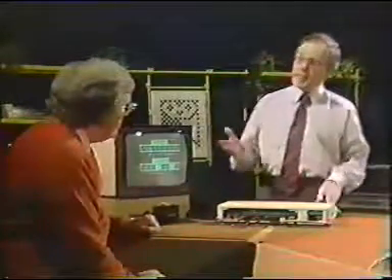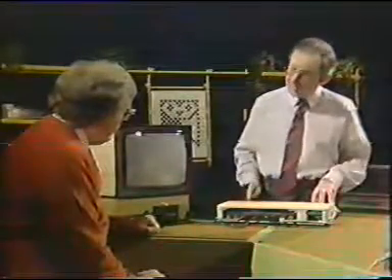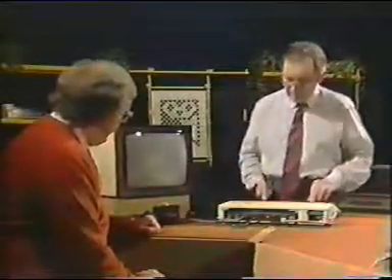Now, we're actually running a program at the moment, but I could stop the program and talk directly to that location. I can say the contents of 65,120 equals some number like 255, for example, and that turns all the lights on. That's the biggest number you can store in that one byte. So we can put digital information in it, we can switch on the lights here. That's right. So what?